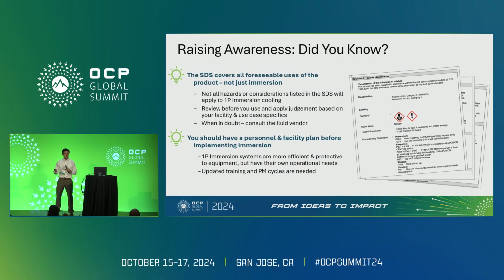So a big point that we wanted to touch on in making any sort of safe handling guidelines for immersion cooling fluids is that whenever you look at an SDS sheet, it is actually covering all of the foreseeable uses of a fluid. It covers hazards for different uses that might not actually be relevant to immersion cooling.